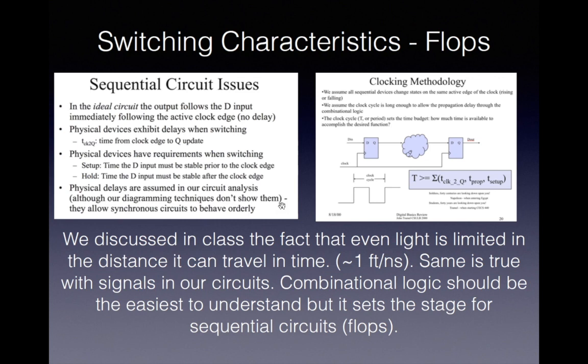Flops are the same. With a flop, what's different is that we have the concept of a clock. And the clock will have a frequency and a period. And I continue to push that I expect you to be able to, in simple terms, move between clock frequencies and clock periods. But it's the clock period that sets up the budget. And the budget means I have to get all my work done in one clock period. So what are the consumers? The consumers are what takes time.